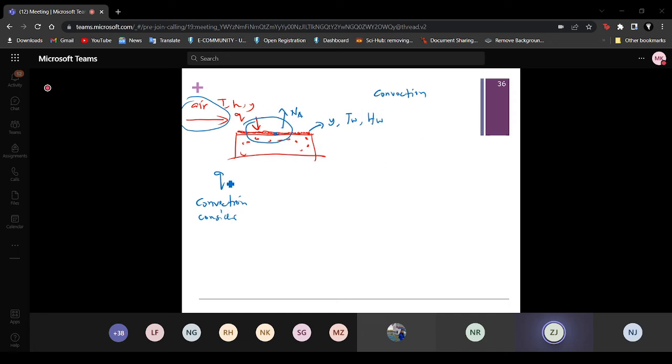Okay, so for convection, for Q, the heat for convection, I think everyone knows because you already took heat transfer. The heat transfer coefficient by convection, I put it as C, QC. Because later we have conduction and convection, we can directly put different notation. Okay, Q is equal to HC A (T minus TW).